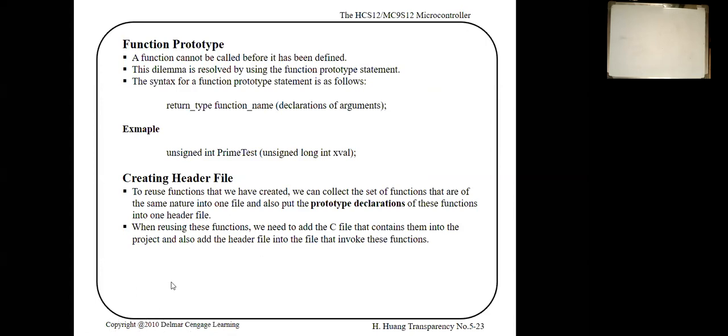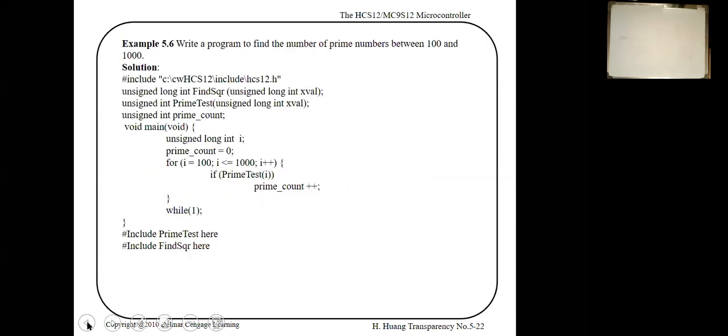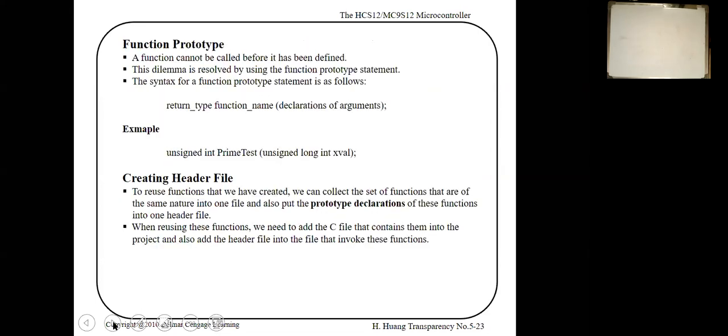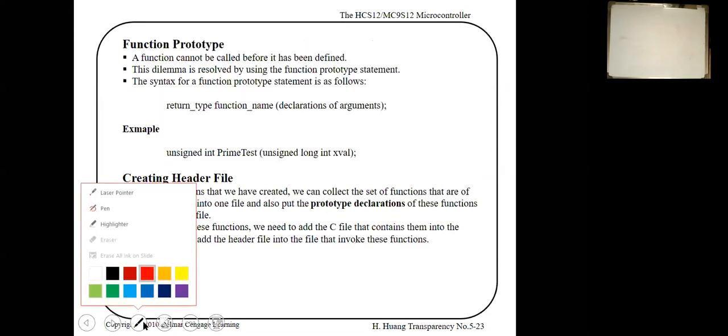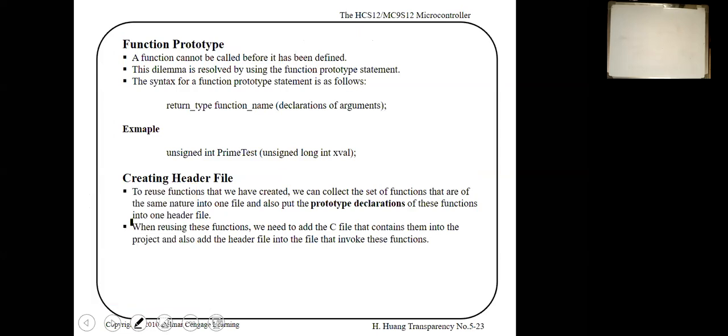Okay. Another thing that might be useful for you is the header files, where you can define your own header file. You put your definitions and so on if you need. We already used header files when we write include derivative.h in Code Warrior, or derivative.inc, which includes all the equate statements that define the registers and the bits inside these registers for the HCS12 microcontroller.